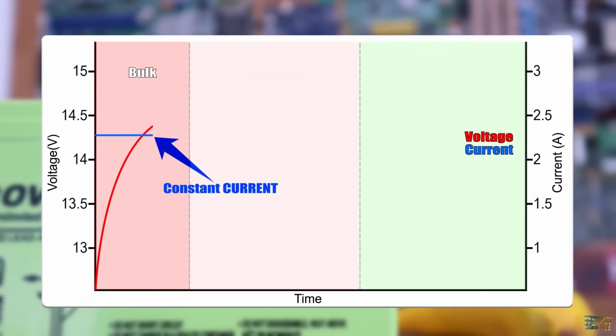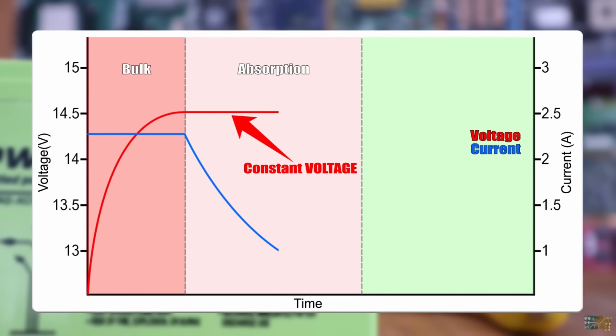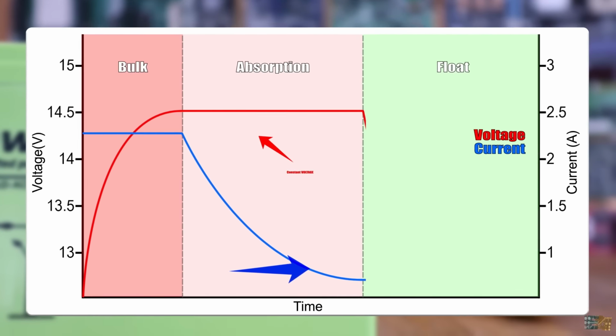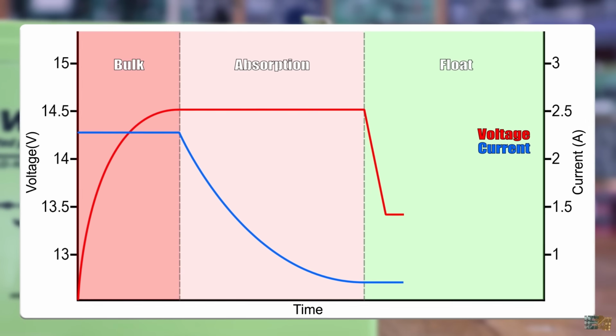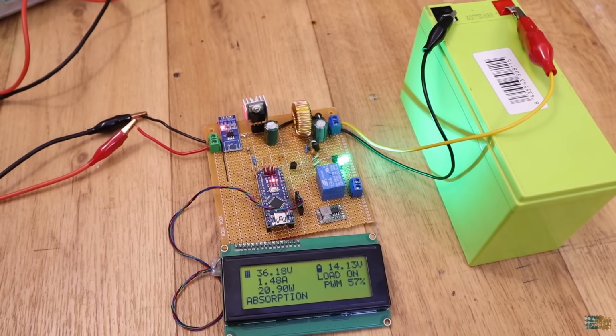Basically it will charge in the ramp mode, which is called bulk. Then it will have an absorption time and then a float or compensation time, where basically it's almost at the maximum voltage and you only have to keep that voltage. So in that case, if you want to get more power, you can't, because that's the maximum power that the battery will take. So even if your panels can give thousands of watts, you can't put more power into the battery because it's already at the maximum point, or it can only take that amount of current because it has to go first into a ramp. So what you could do is add more batteries, but that will increase your costs.